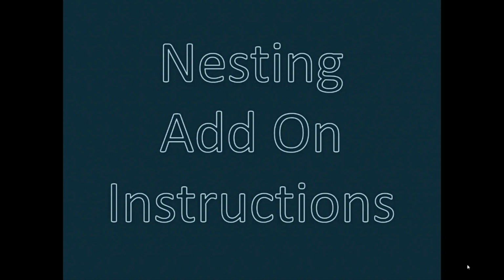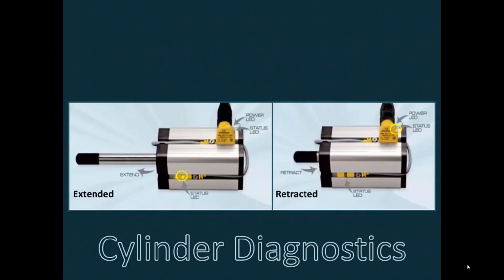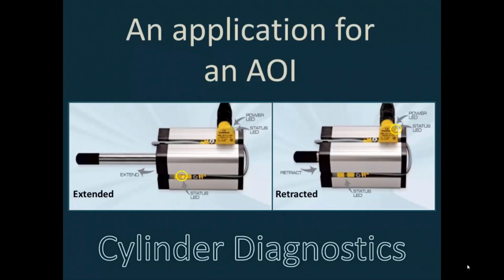In the industrial controls world, there are many things to control. One of them is motion, and the simplest is to position back and forth, in, out, insert, and remove type motion. Simple two-position control. This is normally accomplished with a pneumatic cylinder. There is a piston that can travel back and forth inside of a cylinder that has a port on each end. Compressed air applied to one port forces the piston to extend the rod connected to it. Compressed air applied to the opposite end of the piston causes the cylinder to retract the piston.